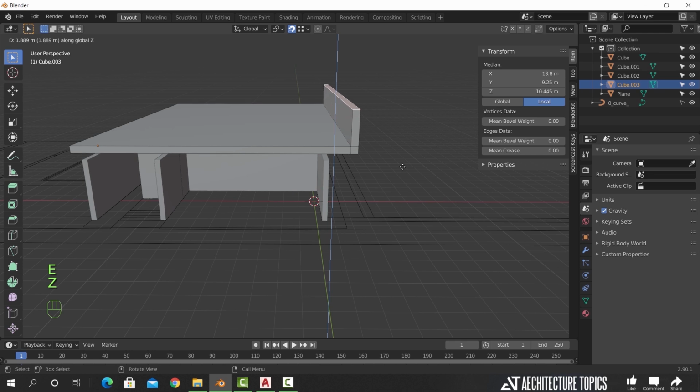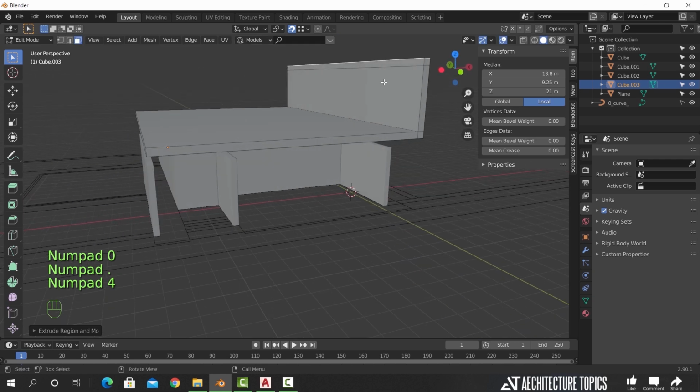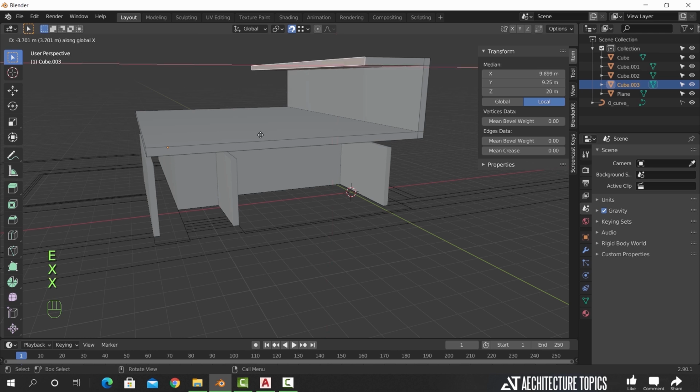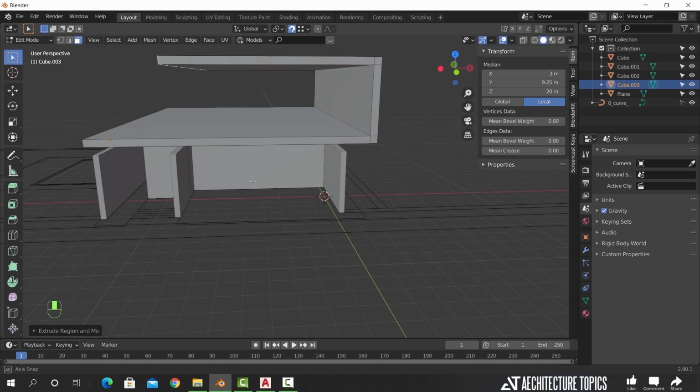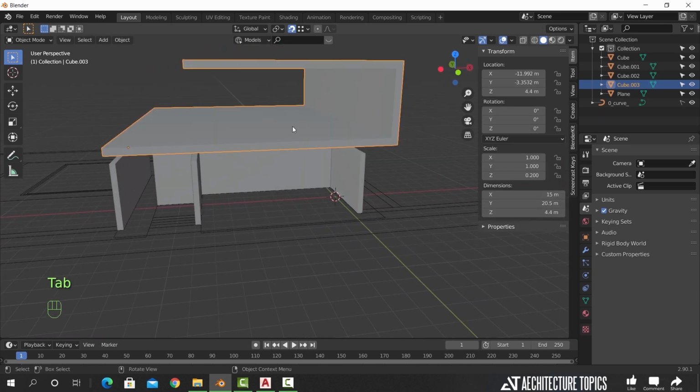First part will be the walls, and with a height of 3.6 meters. The second extrude is for the ceiling, with a height of 0.4. And again, with the same extrude command, extend this face to cover the mesh from the top. I will extend it to this wall for now and see how it looks.